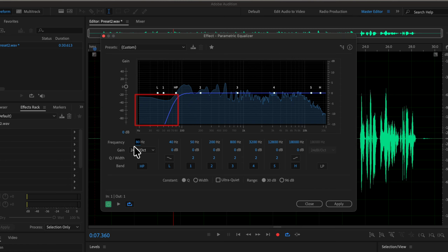You can see the wave jumping in that area. That is part of the frequency distribution of this recording, so we can often see something below 80 Hz. But if that is not the voice, then what is it? That is usually some kind of noise, low rumble or low frequency noise. And by using a high-pass filter, we can reduce the low rumble and low frequency noise.